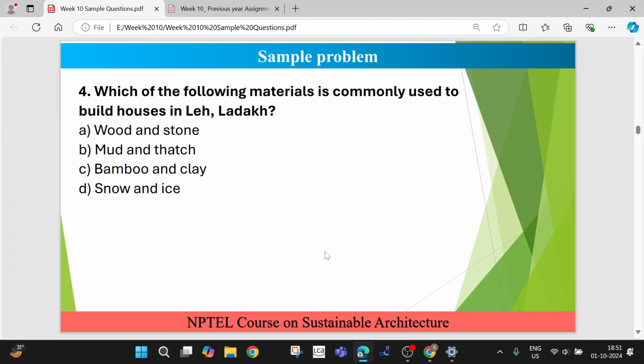So there will be some constraints of construction as well as availability of material. And apart from that, as I was saying, it depends on how long the snow is there, or how long this cold climate condition is prevailing. Based on that, you will have to opt which objective is most suitable for you, or how much weightage you want to give to which objective, whether trapping most of the sunlight for most of the time of the year is good, or if there is snowfall only for some period of the year, whether they will go for that. So those decisions people need to take.